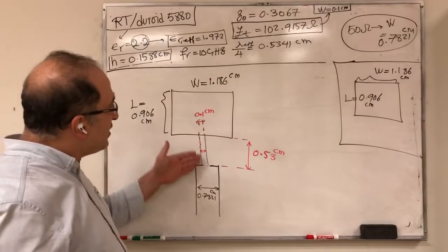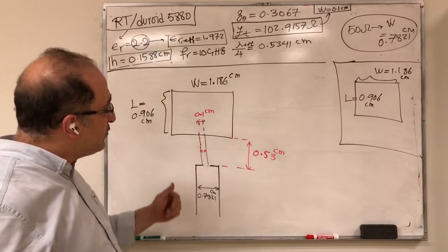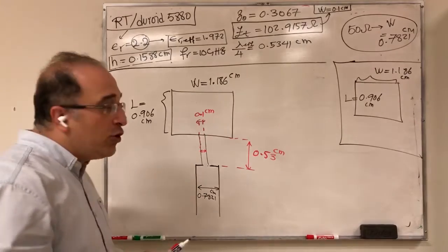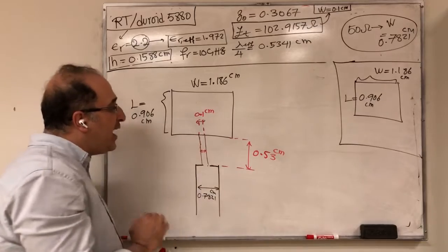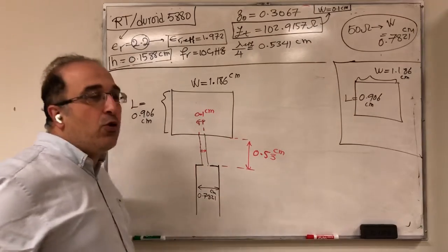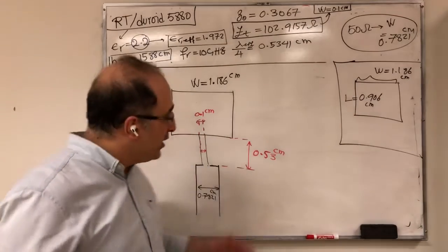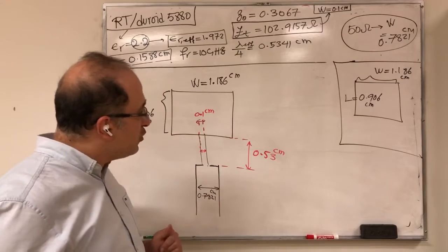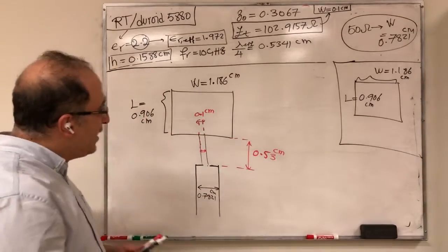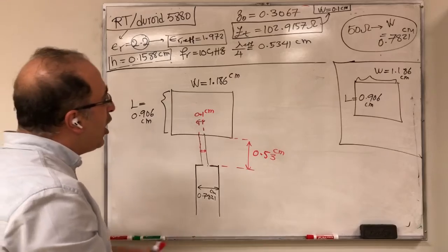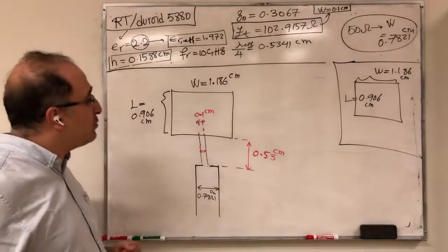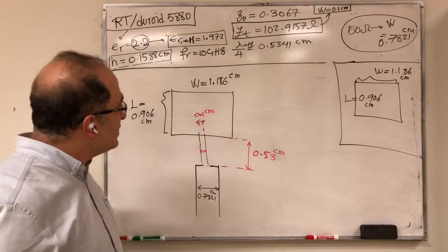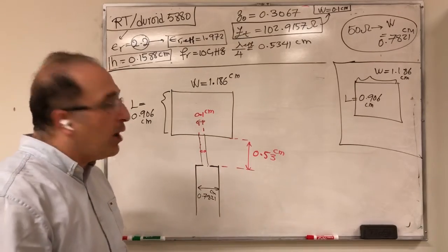But this quarter wave transformer style of feeding, you don't go inside to feed. You actually feed at the edge, but then you have a quarter wavelength transformer to connect yourself to 50 ohm. And then remember that all of these are on top of a substrate, and behind you have ground plane. So this is something to keep in mind. Thank you.